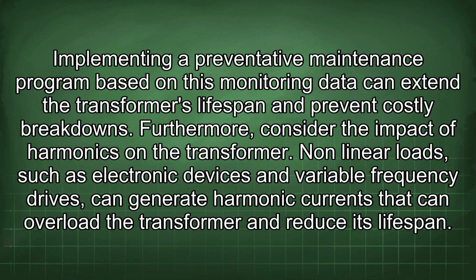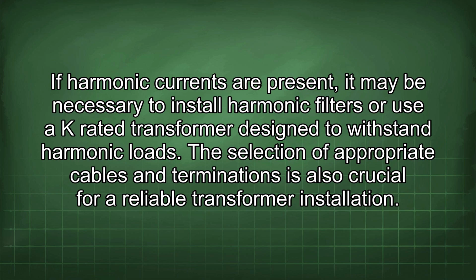Furthermore, consider the impact of harmonics on the transformer. Nonlinear loads, such as electronic devices and variable frequency drives, can generate harmonic currents that can overload the transformer and reduce its lifespan. If harmonic currents are present, it may be necessary to install harmonic filters or use a K-rated transformer designed to withstand harmonic loads.